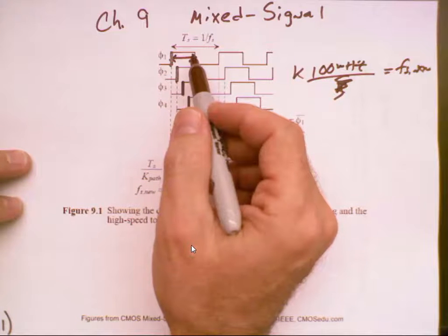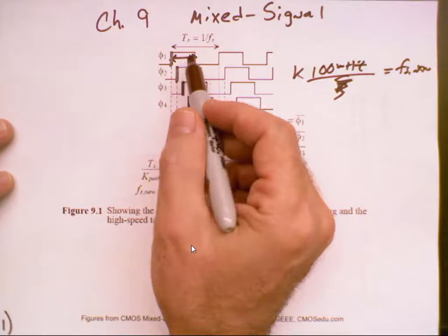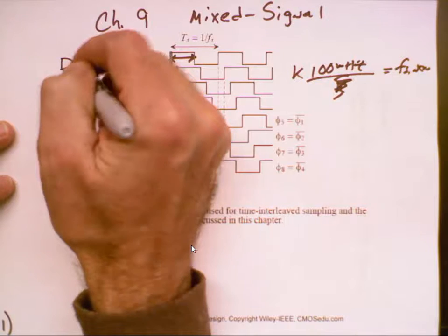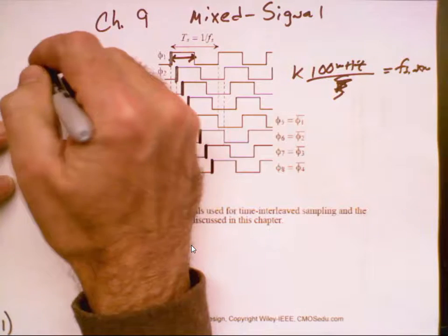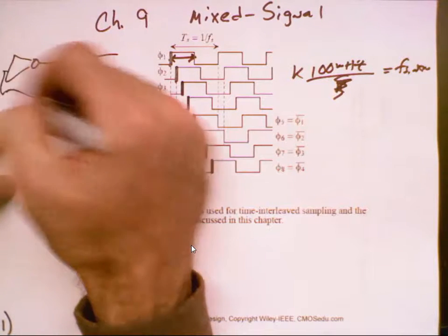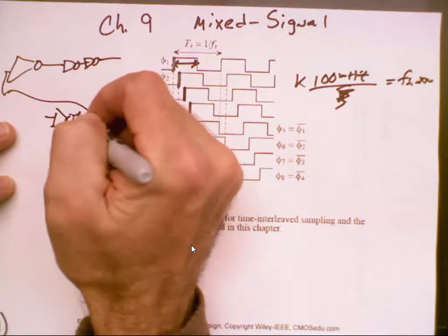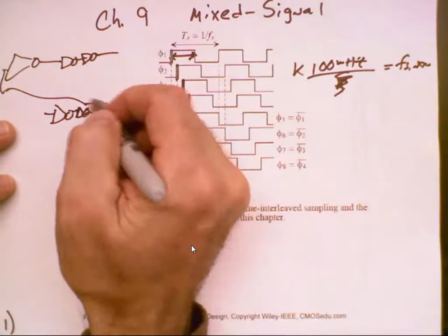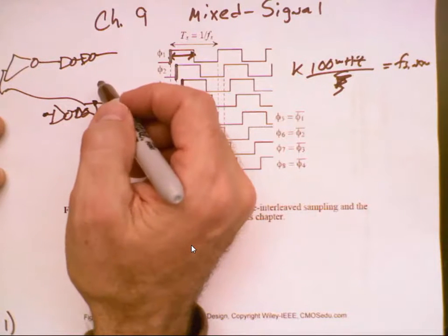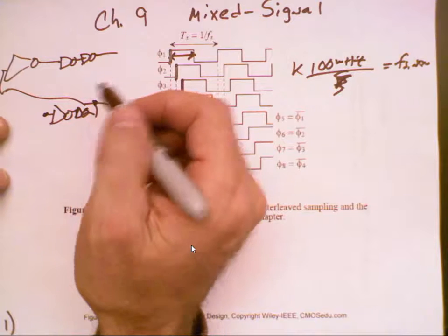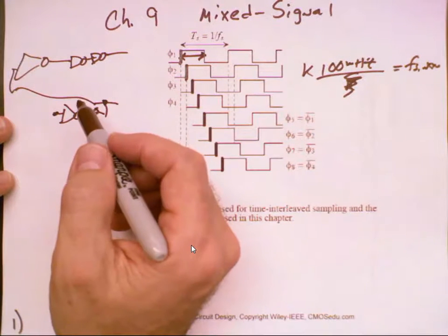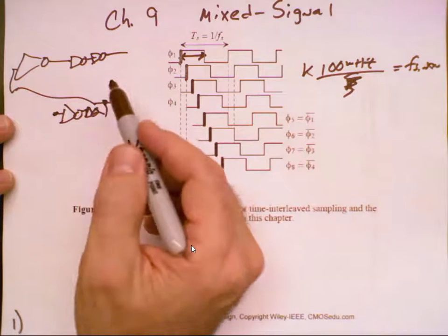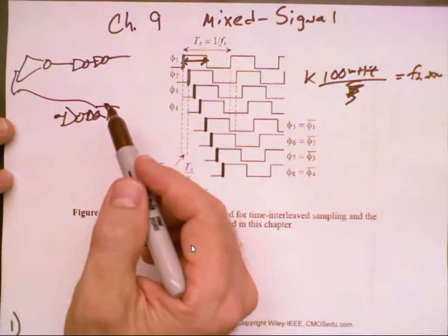So if I look at the delay stage, here are your inverters, here's your NAND gate, what happens to the duty cycle if I change the connection of the NAND gate, say from here to here? If you say it'll change the duty cycle, then I'm going to ask why. I'm not going to ask hard questions, but you can't just say it's clocking and not understand you need an odd number of inversions, or trivial questions like that.